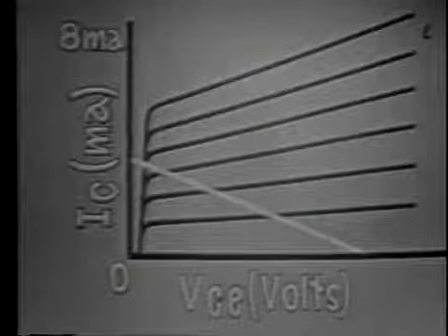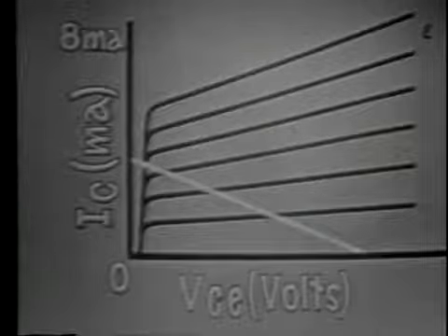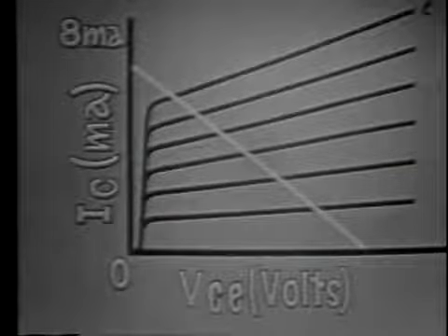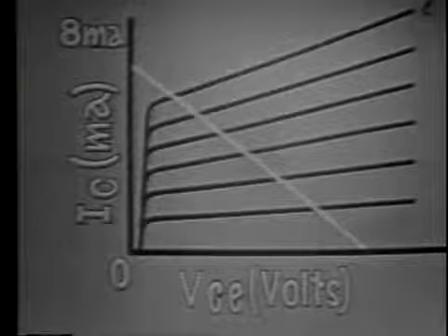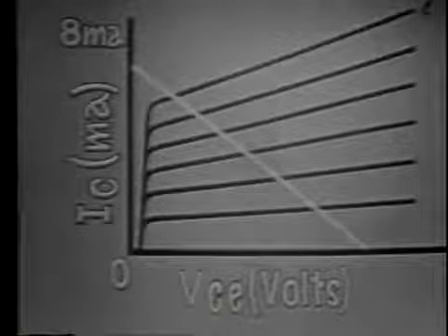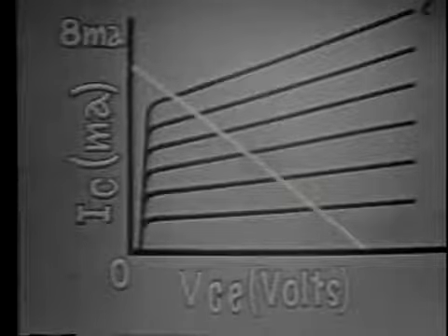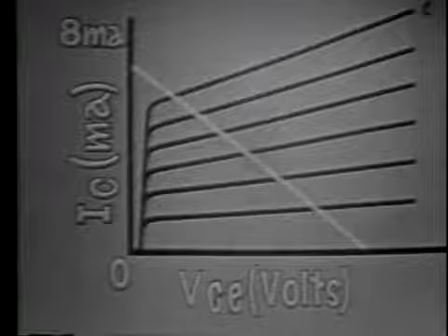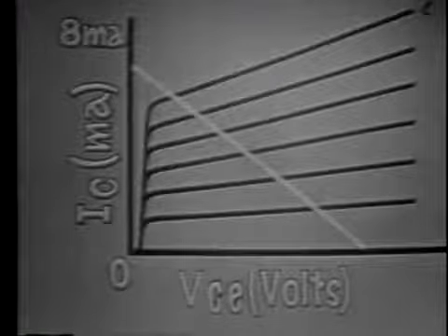If we started here with a large resistor, say 4K ohm, and decreased the resistor to 2K ohm, the opposite would have happened. Current gain would have gone up and voltage gain down. An important conclusion is that a current amplifier would have a relatively small collector load resistor, and a voltage amplifier would have a relatively large collector load resistor.